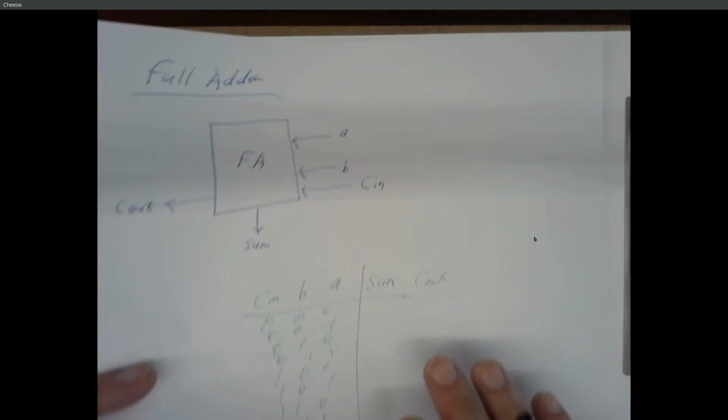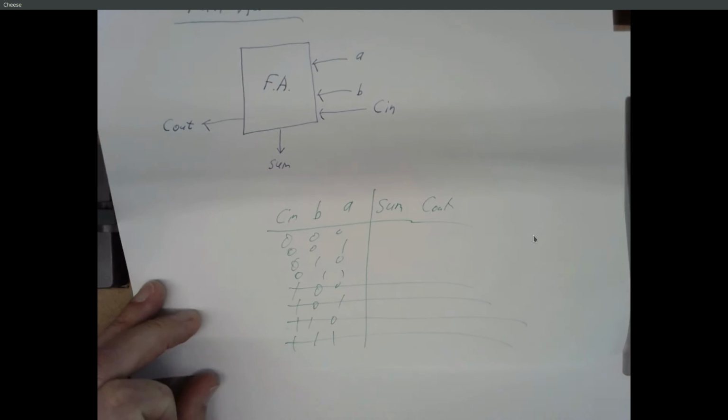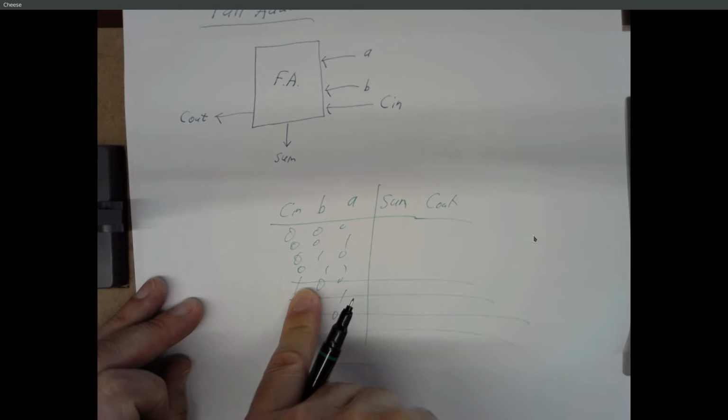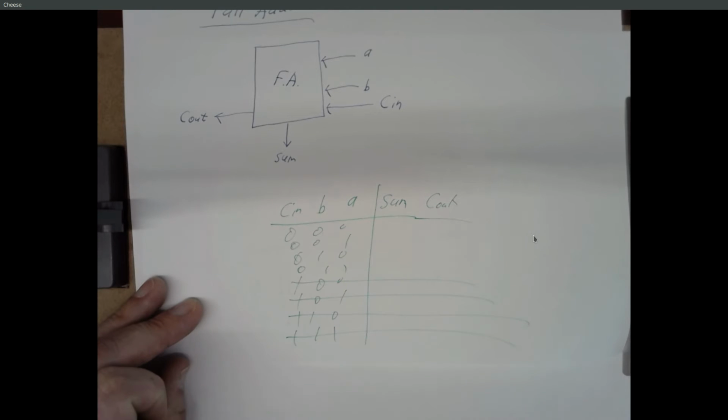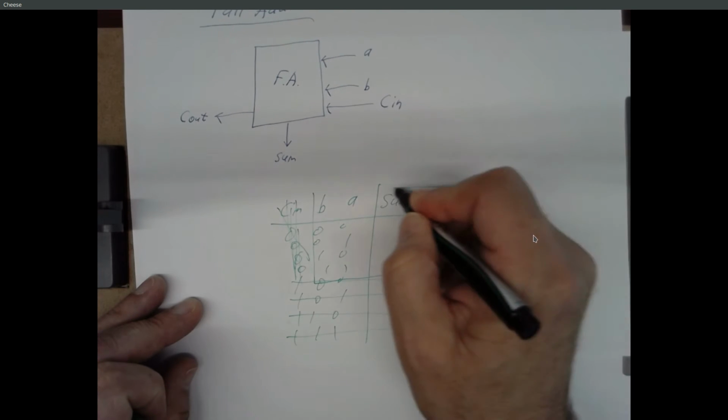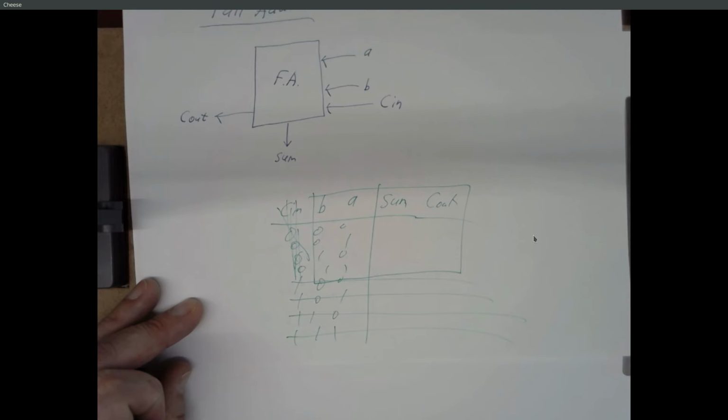But in the case of this first full adder, the carry in is always 0. We don't need to do any of this, because we know we're never going to have a case where C in is 1. Well, if we know C in is always 0, we don't need that to be an input. So guess what? That first full adder is a function of just 2 inputs.